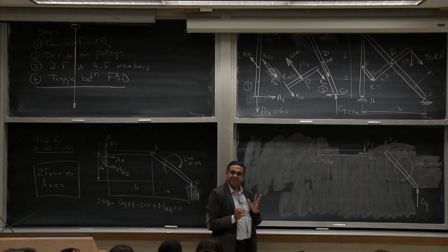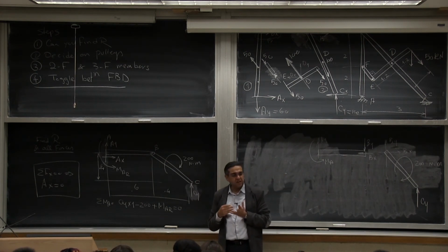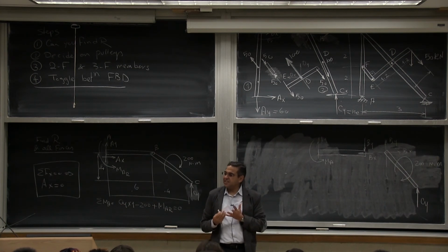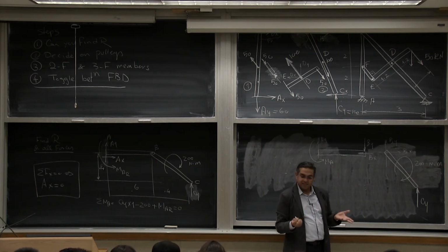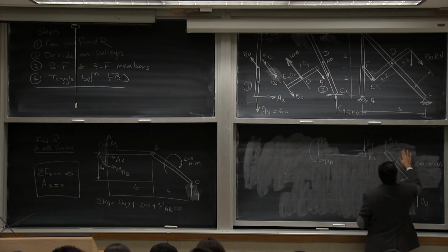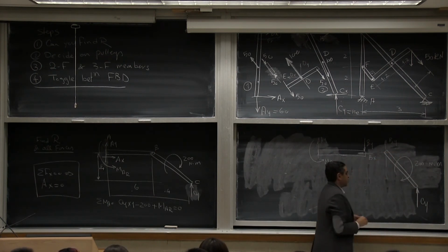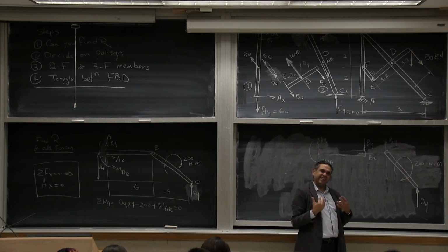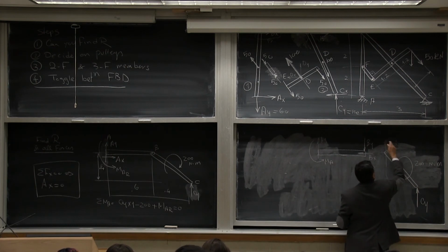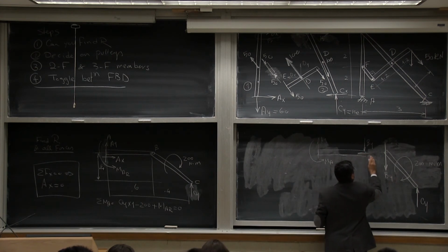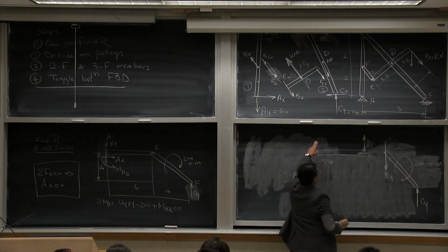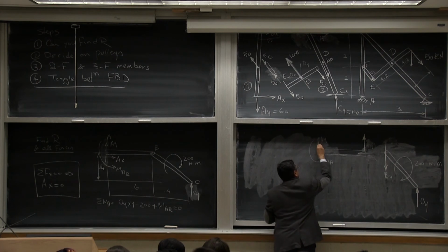So if I go here, before I draft AX, BX, and BY, I should start thinking a little bit. Is it logical to have a BX? It's not. So I should not bother myself and remove that from my draft. And in terms of BY, is it logical to assume that's going up? No, it's not. It's going down. And so I remove this here, and I go this way, which means AY must also be going down.